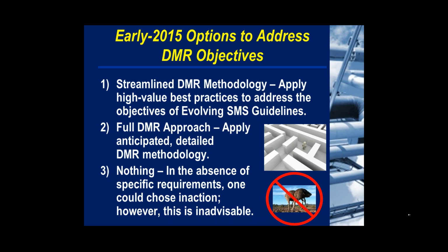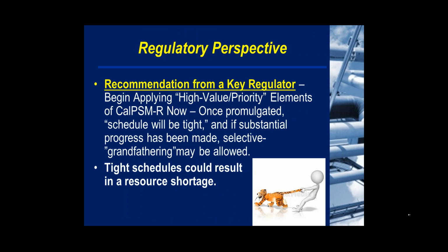As I mentioned before, several agencies were involved in updating the regulations to address this, and the real focus is on improved hazardous material containment integrity: piping, vessels, pump casings, flanges, everything that's your containment for your highly hazardous chemical. That's what damage mechanism review is all about. So again, the idea is what do you do about that? And I'll get back to the first item on this screen in just a minute.